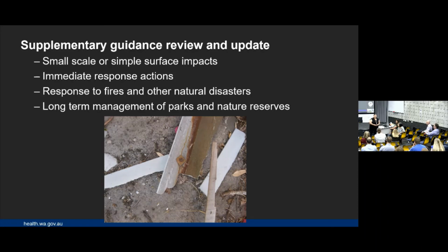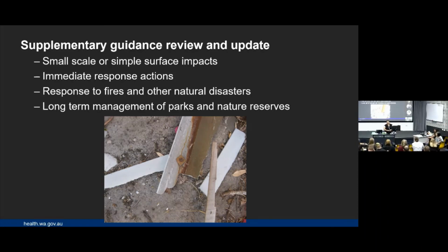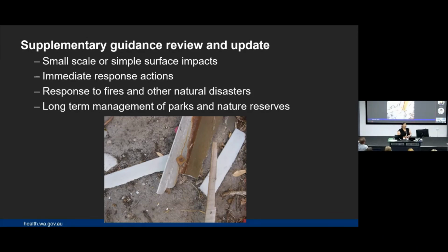So you need to have someone who determines whether those fibre bundles in soil are trivial contamination. You'd have to have all the lines of evidence associated with making a decision. It's possible to make a decision that that's trivial, but you would have to support it with the lines of evidence about what state the site is in, what other sources there are, whether there's been removal in the past. All those things would come into play in making a decision. So there is discretion in that decision. And that would be the contaminated sites assessor or an asbestos assessor. Yeah, okay, thanks. That's good.